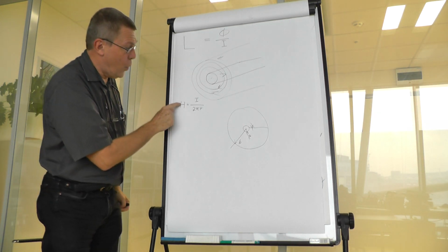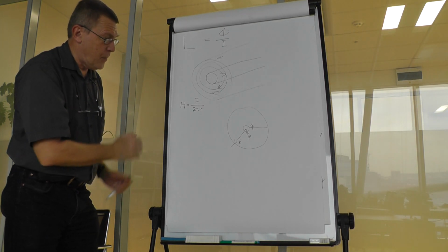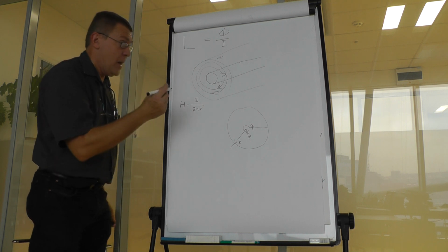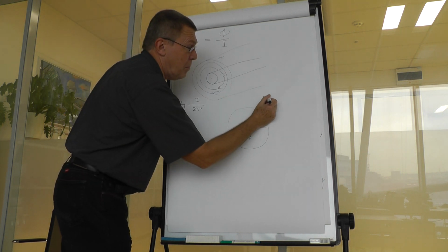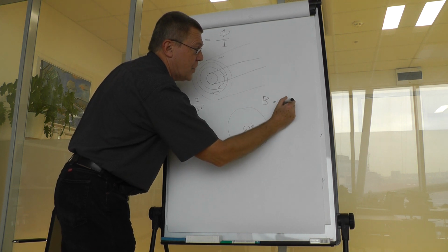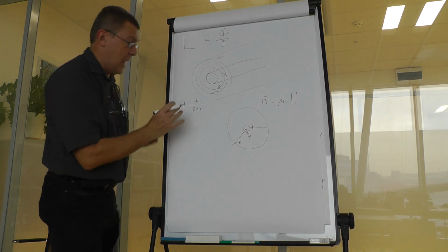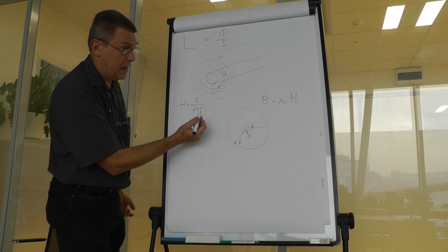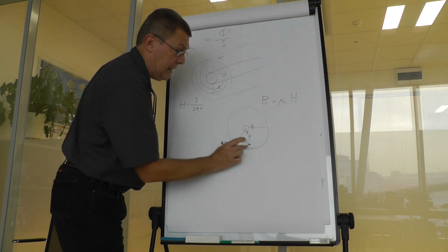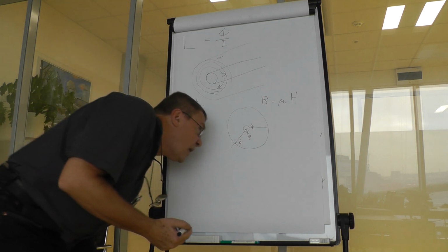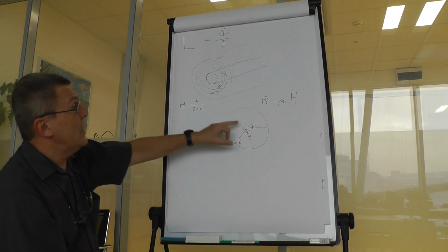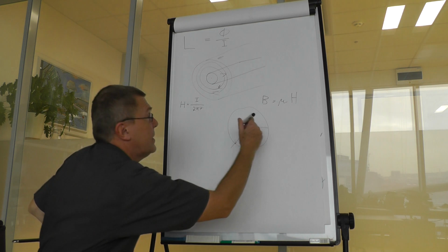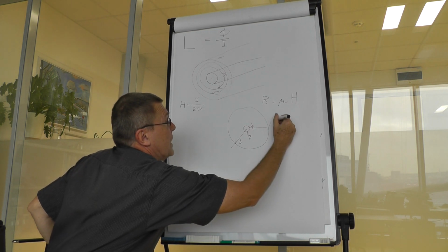But at the time being, we have this equation for magnetic field, and to find out the flux density, we have to multiply that by mu, which is the permeability. So the flux density would be I mu over 2 pi r. And that holds for the inner part of the coaxial cable. So now we would have to integrate this over a surface which is radial and in that direction long for just 1 meter.